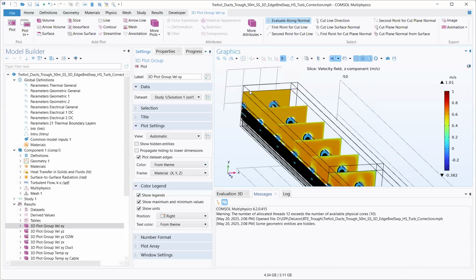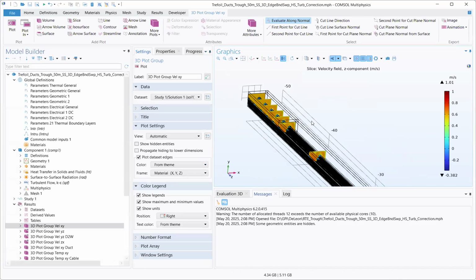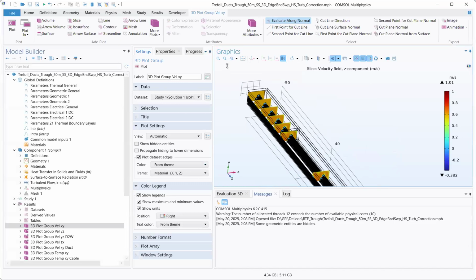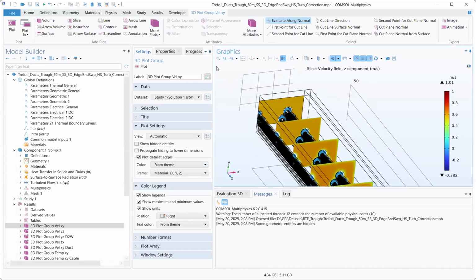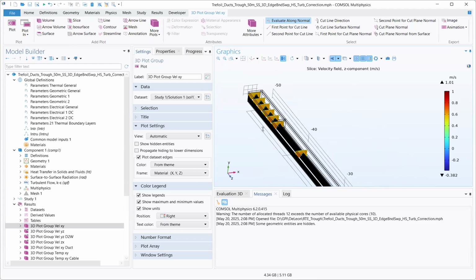There is a difference between the entrance of this trough and the exhaust. So air flows naturally, by natural convection, by pressure difference from in to out at about 1 meter per second in the steady state. That's what we measure. But of course, it becomes non-uniform at some point.